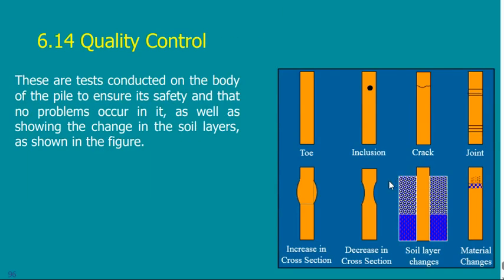This is very important. Quality control is very important. As we said before, the pile loading test is very important. I do these seismic methods to check the pile from inside. I do it for all piles, not a limited number of piles.